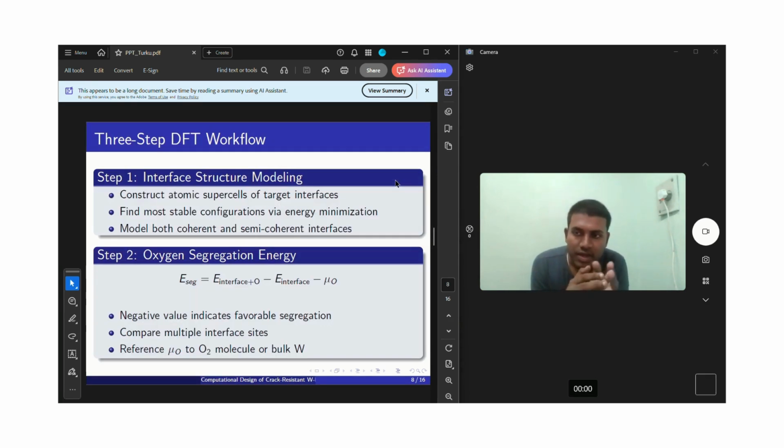Moving on to my workflow, it includes preparation of the bulk unit cell, for which I prefer using the Atomic Simulation Environment, which I usually use in my work so far in materials science. Using ASE, I can create the bulk unit cells. I prefer using VESTA to create the surface slabs. We need to look for matching surfaces. Tungsten being BCC and niobium carbide being FCC, (100) is the preferred low energy surface of contact. We need to stack them up at this point. So this is the preferred direction.